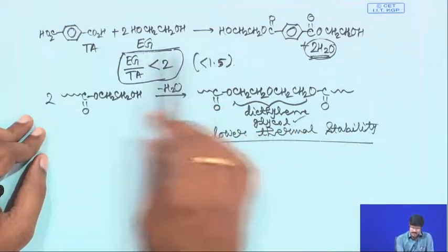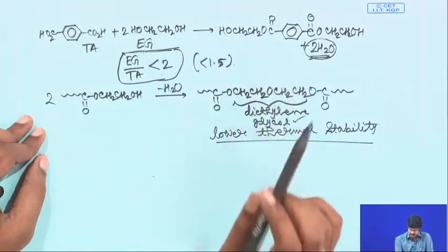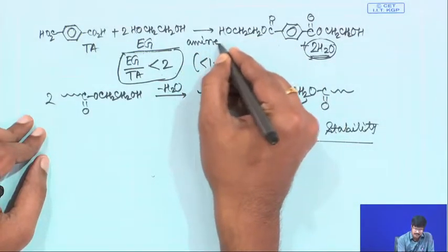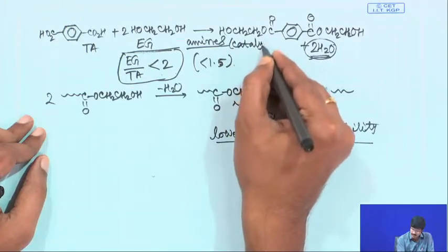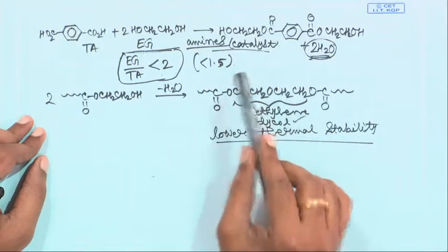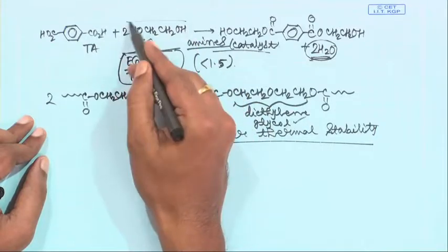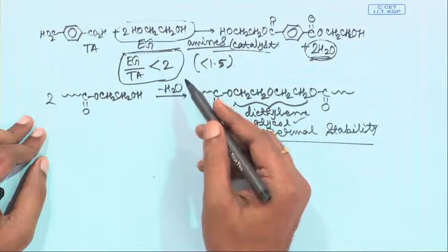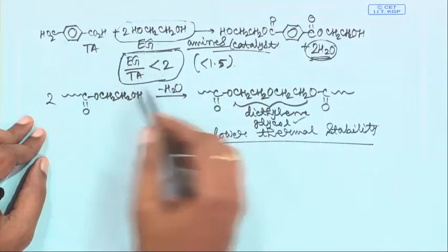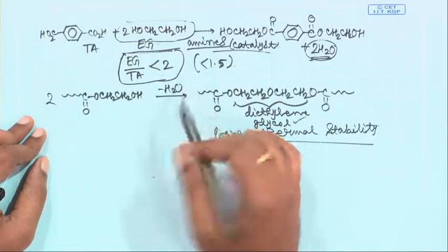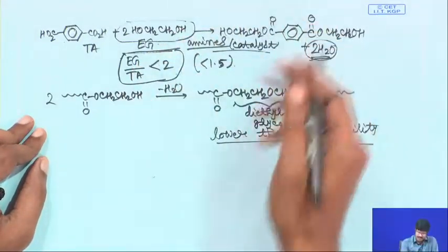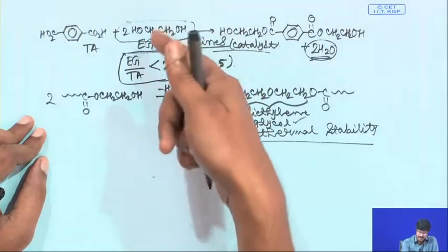Now, the direct esterification reaction is possible without using catalysts, but if you use some basic catalyst, say some amines, then this reaction can be accelerated. So, this is a catalyst you can use, or you could use some transesterification catalysts also. Once the esterification is done, you have to distill off this ethylene glycol. This reaction is done under high pressure, of course, because terephthalic acid is not very soluble in ethylene glycol. After the reaction, you release the pressure slowly, so it comes back to atmospheric pressure slowly, and the temperature is simultaneously increased, and the excess ethylene glycol has to be distilled off.